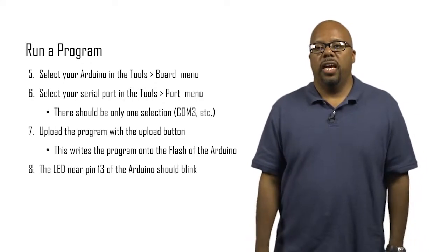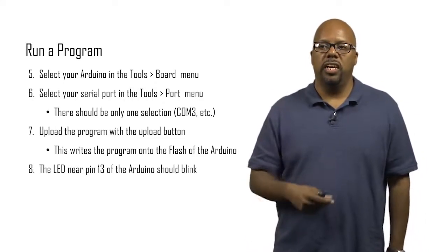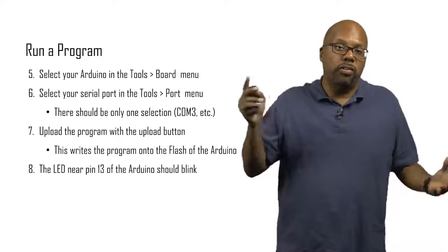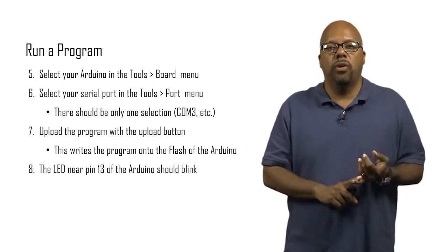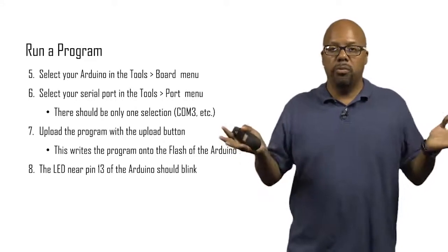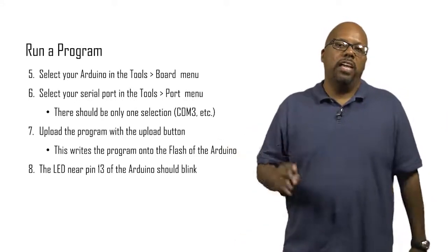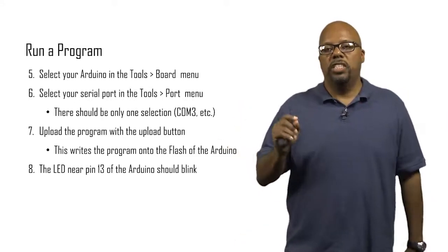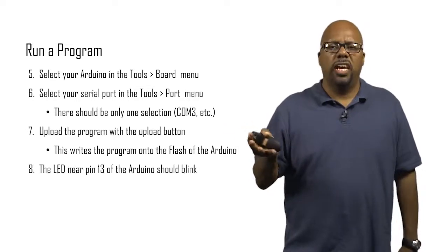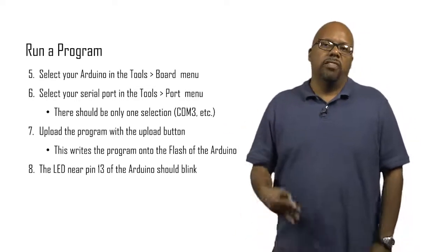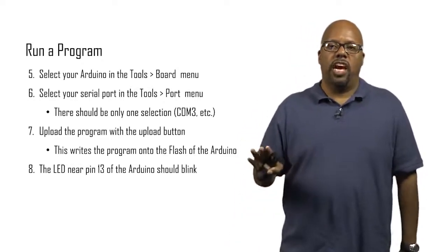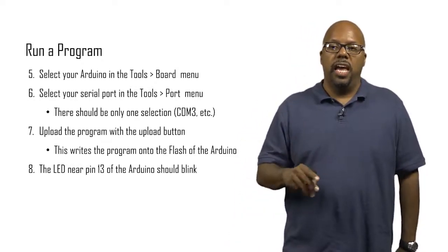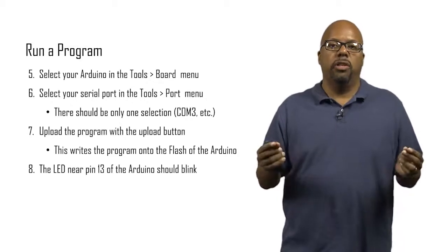Once you've selected the serial port, you upload the program. You press the upload button on the IDE, and it'll compile the program, checking for errors. The Blink program will have no errors. It'll compile it, and then it will upload it. That'll take several seconds, 10 seconds, let's say. Some lights will blink on the board quickly, and then they should stop blinking, and it should be programmed. You should see a little message that says, done uploading.